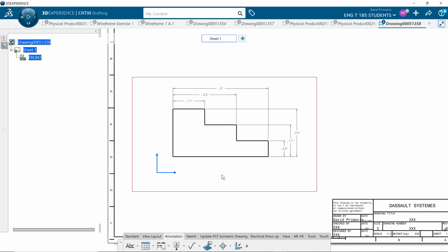This is called stack dimensioning, baseline dimensioning, or datum dimensioning. It's all coming from this feature right here. So another term is feature dimensions, where you're dimensioning all from this edge. Notice there's only one extension line going to this end, only one extension line going to this end, only one extension line going to this end. All 3 extension lines go from the bottom, making this my feature dimension or datum dimensioning from this line and then from this line over.